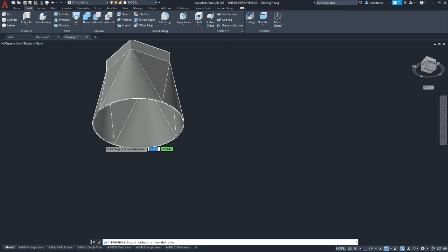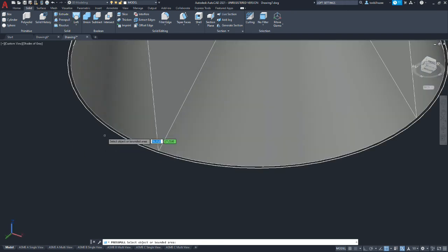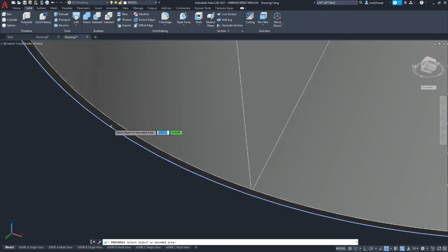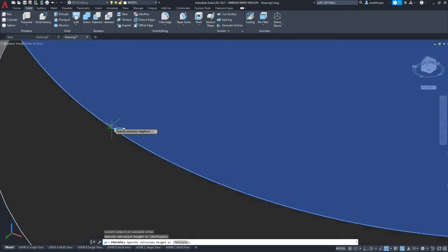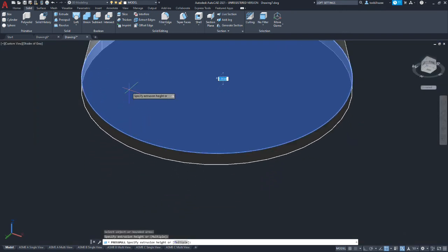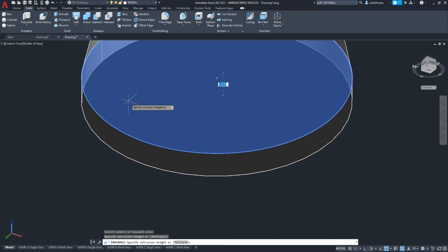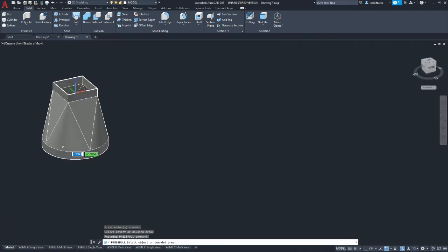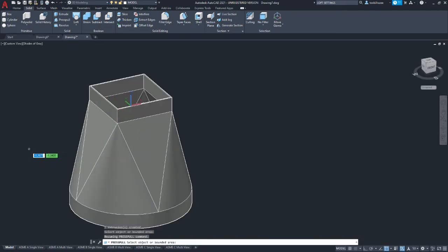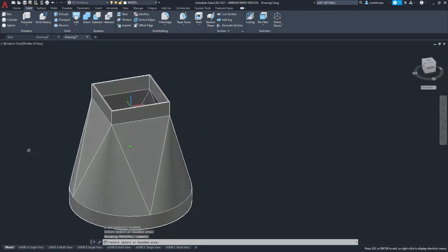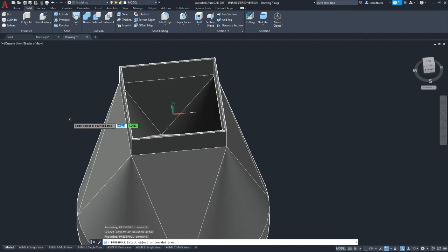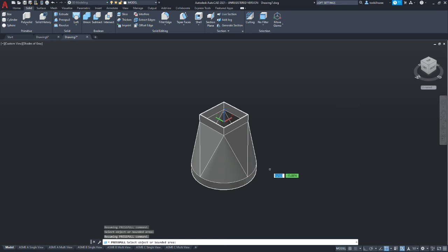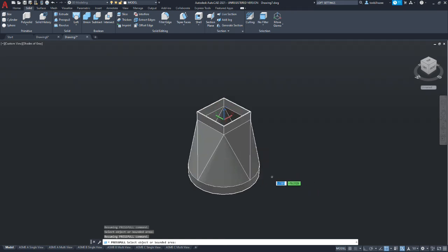Okay, now we're going to press pull the bottom, and we're going to press pull that down 2 inches. You may have to draw an auxiliary circle there if the geometry you had isn't working. But there's our solid bottom. I'm going to go to the home position just to center my screen. And it's a great time to save.